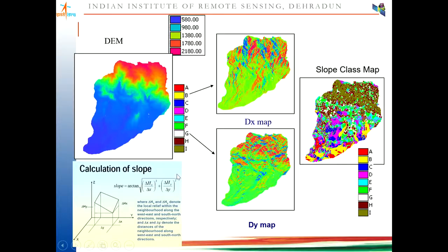So all slopes more than 45 degrees are considered more than 100. That's why in a digital elevation model you will also get more than 100 or 300 slope class, although in nature we know the maximum is 100%.